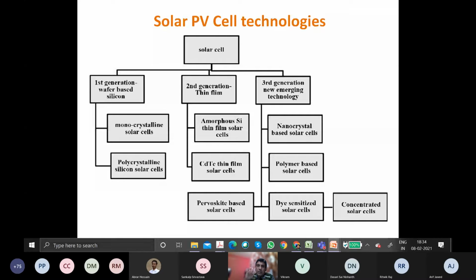Right. So let's say the energy of the photon falling on the cell is around 1.2 electron volt. Now the band gap energy of the material on which it is falling is, let's say, 1 electron volt. So what will happen? The falling photon is 1.2 electron volt, so it will absorb 1 electron volt, and it will go to the next state. The electron and hole pair will be liberated and they will move across the junction. But the remaining 0.2 electron volt is wasted.